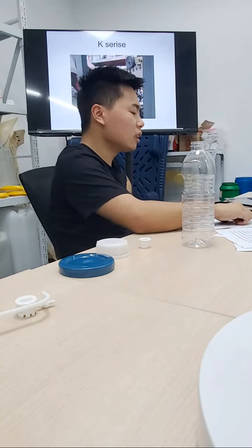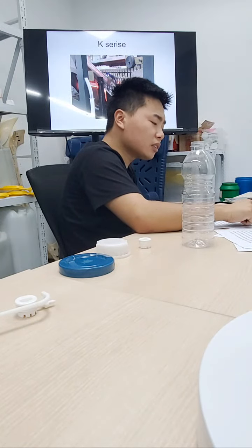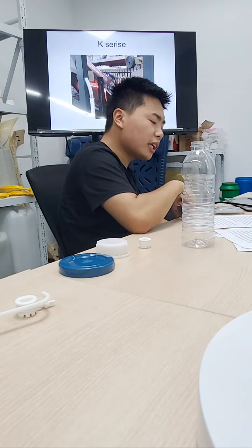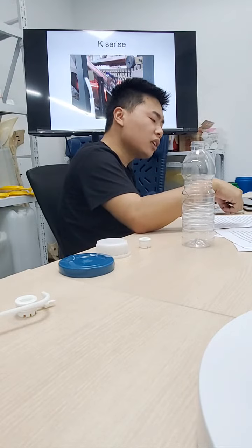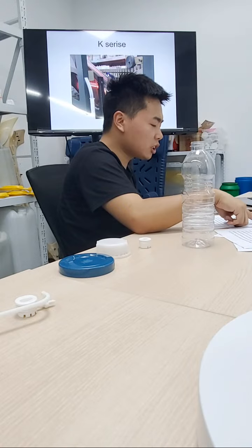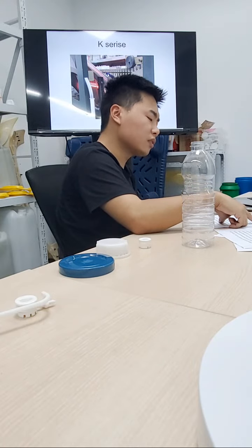They have a distance transformation design. When the platform is loading and heating, the distance of each platform is 40 millimeters. As the bottle passes through the heating part, the distance will start to change. The platform will be taken out from the chain to the blowing part. In this process, it will be changed to the suitable distance, so it can save very big energy. It saves about 40% of the electrical consumption.